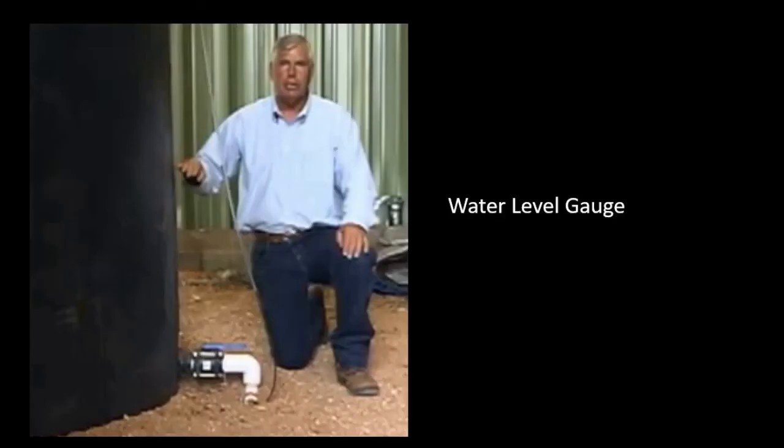So he came up with an ingenious way to be able to know how much water is in the tank. Now you could just thump on the tank and hear the difference. It'll go doink doink or donk donk, and kind of get an idea. But this is a little clear, flexible tube that's hooked into the outflow, and it goes up to the top. And when you open that up, the water level will go up the tube to the level that's in the tank, because it'll all level out. So you can look at the tube and you can tell exactly where the water level is.